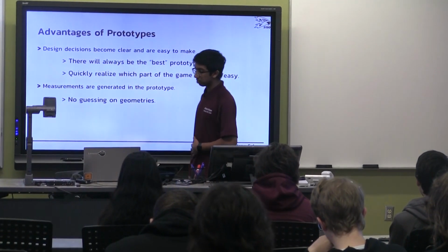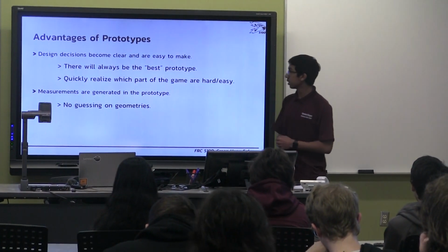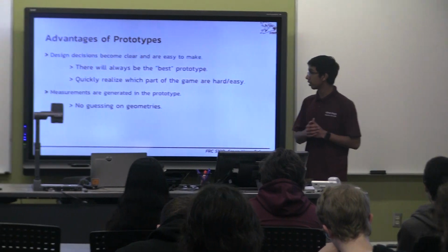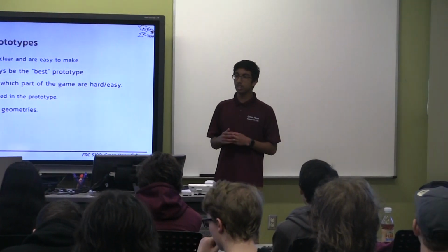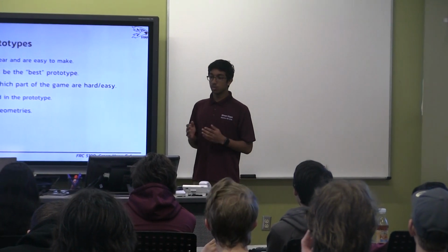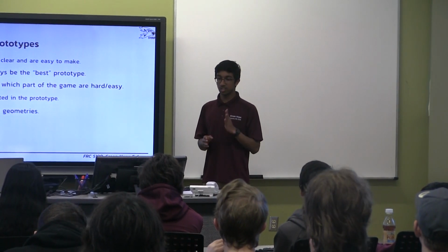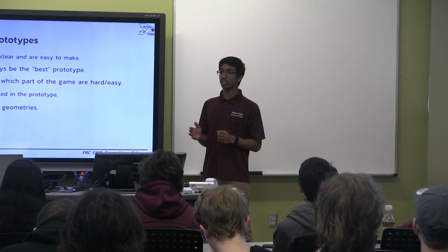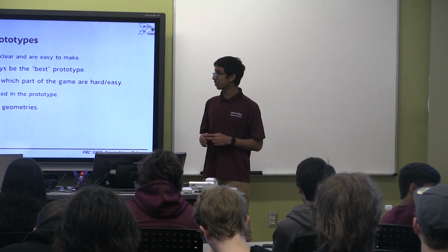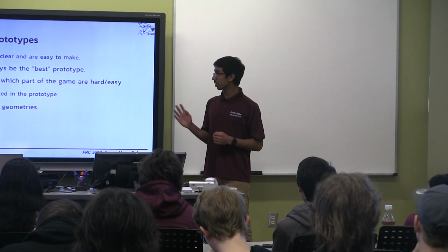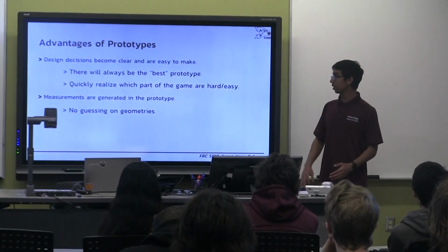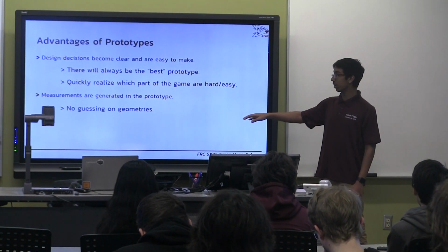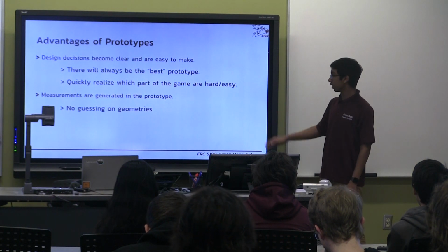So what are the advantages of prototyping? With prototyping, the design decisions will become clearer and easier to make. Last year, in 2018, we had a conflict on our team where we were looking at designing either a roller intake or using wheels. It was a good debate for the first 2 weeks. And then instead of arguing, what we decided to do is build 2 prototypes. The one that worked better ended up being on our final robot, which was the wheeled intake.